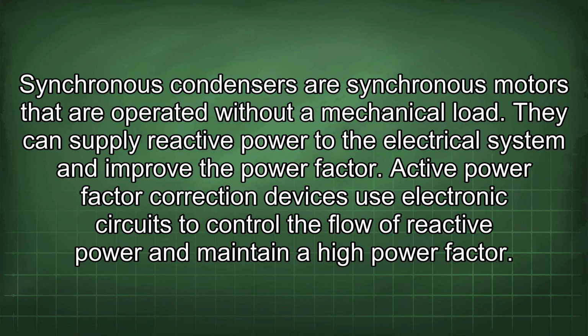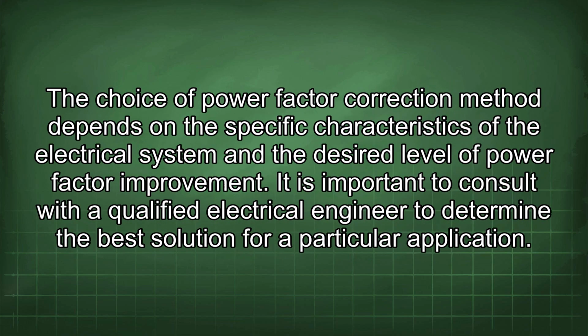Synchronous condensers are synchronous motors that are operated without a mechanical load. They can supply reactive power to the electrical system and improve the power factor. Active power factor correction devices use electronic circuits to control the flow of reactive power and maintain a high power factor. The choice of power factor correction method depends on the specific characteristics of the electrical system and the desired level of power factor improvement.